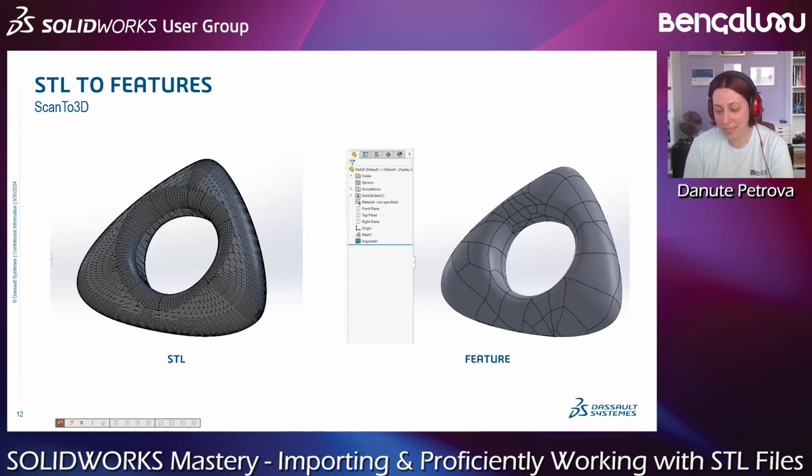It's really amazing, because there's hardly another way to import an STL file with an organic shape into SOLIDWORKS and have it look correct. If you use the other way of import, a solid body without mesh body enabled, there becomes a problem, because you will have all these faces and you won't have it smooth as it should be. But with the basic import with mesh body enabled, you can have it with a nice and smooth shape.